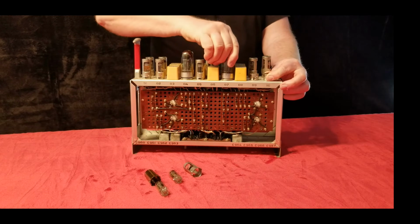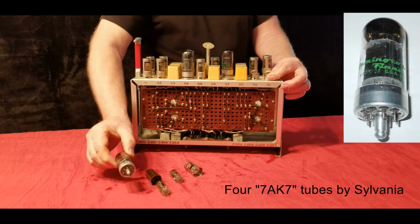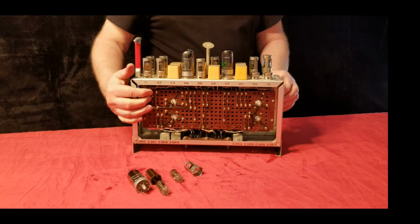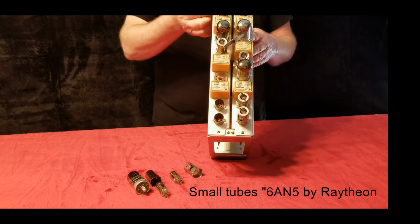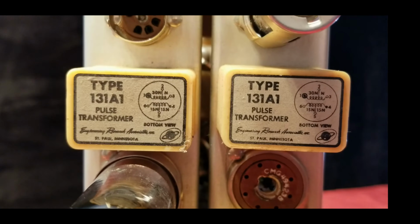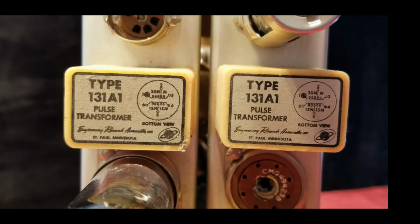There are 14 vacuum tubes in this module. The 4 larger metal-based tubes are Type 7AK7, manufactured by Sylvania, and branded Remington Rand in green lettering. There are 10 small glass tubes, Type 6AN5, branded Raytheon, and these are secured by the metal tubes for protection. There are also 6 of the 131A1 pulse transformers, made by E.R.A.